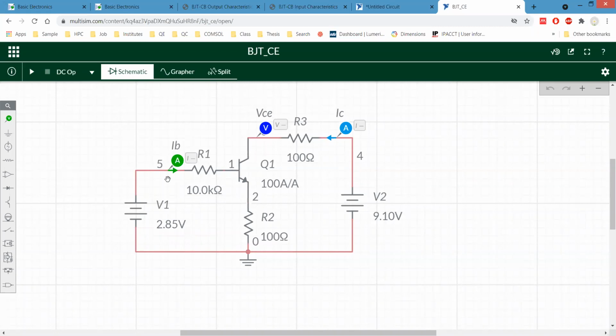So now you can see, in this case, this is also NPN. This is our collector, base, emitter, right? Here, the base is connected to the positive terminal, as the base is P-type semiconductor. P-type is connected to the positive, and only then you can say it is in forward bias, isn't it?